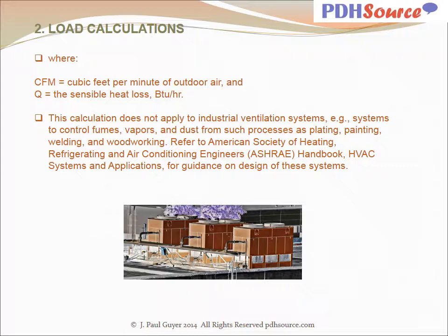The term sensible: there is sensible heat and latent heat. The latent heat of air has to do with the moisture content of the air, and in many locations in the United States you can ignore latent heat.